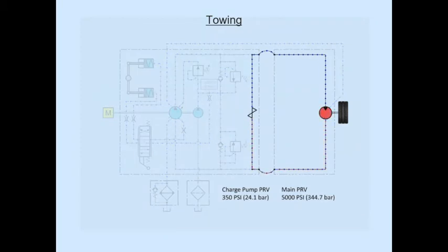Oh, sorry, let me just show you what this is, what a towing bypass valve does. So if you're towing a machine, well, first of all, let's start there. If you don't have a towing bypass valve, don't even think about moving the machine. There's been a lot of very, very unhappy campers because they got a machine stuck that's a hydrostatic drive where you can't disconnect, which would be a bad idea in design anyway. And what they do is they hook it onto it with a D8, some dozer, and then they'll just pull it. You can kiss your transmission goodbye if you do that.